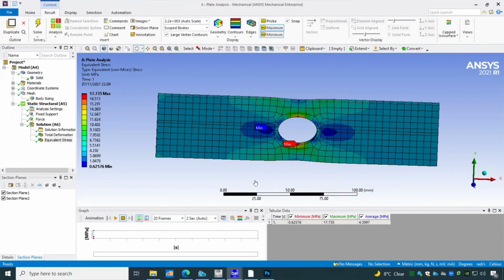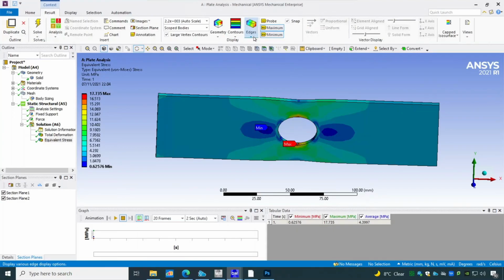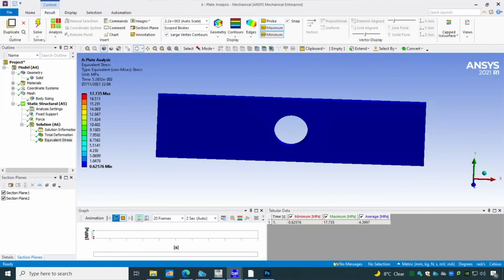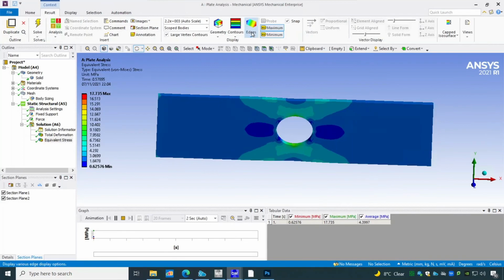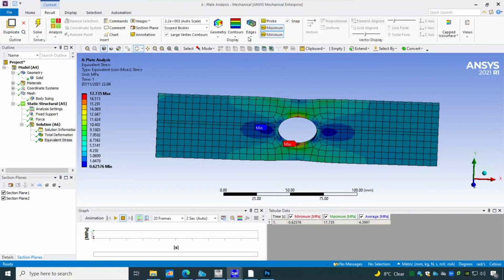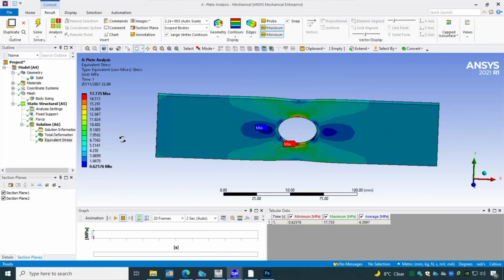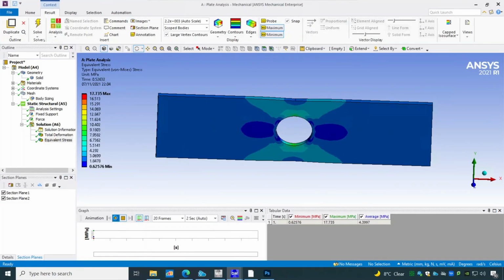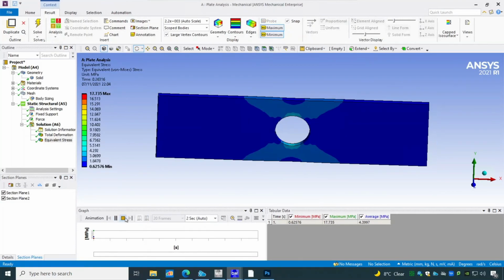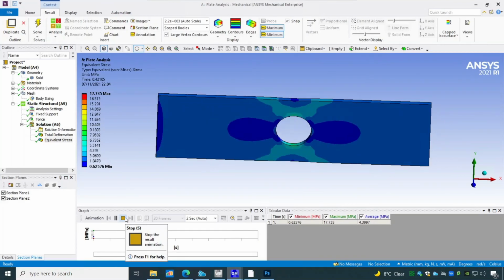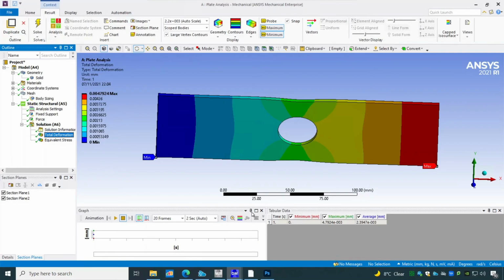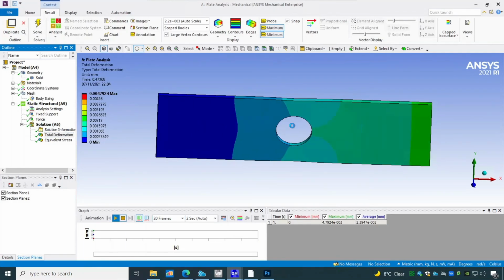The other thing I wanted to quickly mention: if you remember, we compared the undeformed with the actual model, and if I play this video, what you will see here, let me activate the elements and then compare it. It's somehow an exaggerated deformation. How can I check that and compare with the real one in here? It's the same thing. Even if I go with the total deformation and compare that, you will be able to see it here.